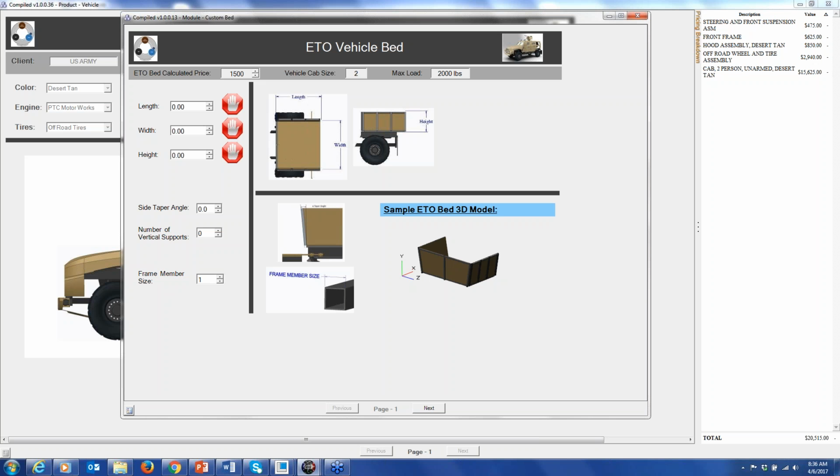You can even go out and call Creo Simulate to run an FEA process if a user wanted to wait. The idea being, if you can put some engineering rules behind this, you could present those engineering calculations back to perhaps a sales engineer, and they might know, hey, my requirement from this customer is that this ETO bed has to hold whatever it is, 4,000 pounds as a max load or 6,000, and walking through this configurator process, you can, again, call those engineering calculations, and the sales engineer might be able to determine if this configuration is meeting a customer's requirements.